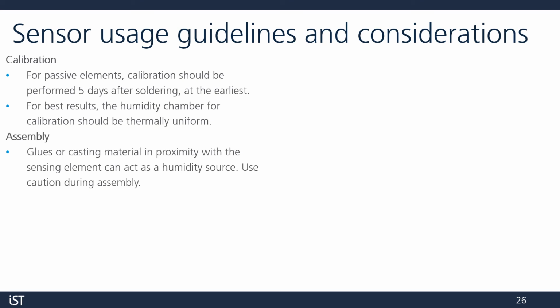Assembly. Be sure that your glues or casting materials are not too close to the sensing area. These can act as a humidity source and affect your measurements.